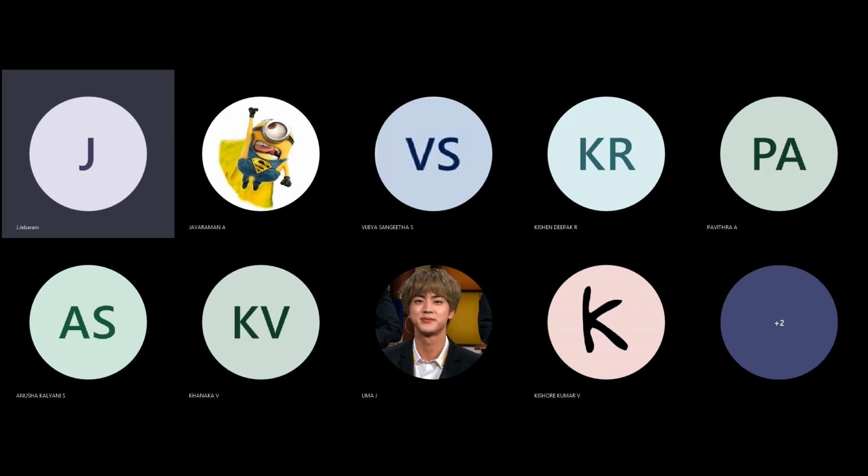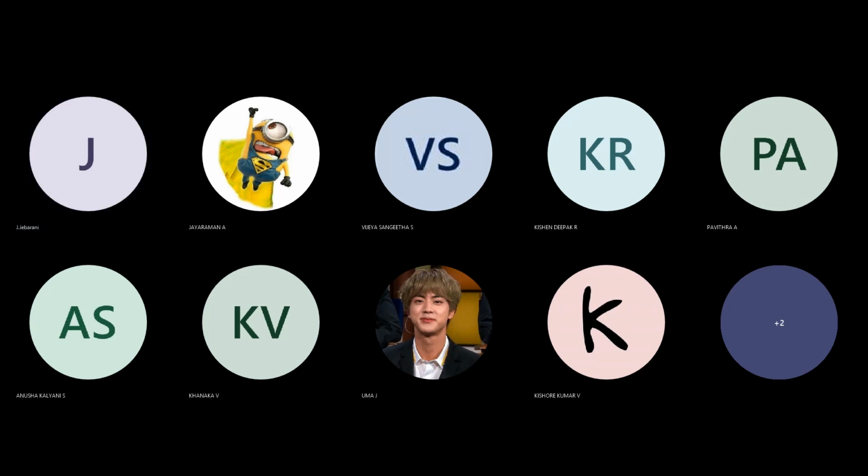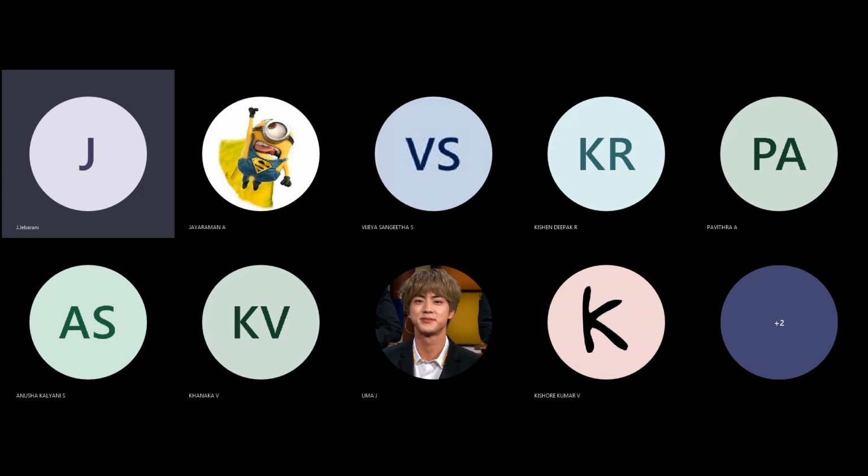And the third approach is called overflow. Here the mold cavity is completely filled with melt and closed off by the wall. Then a separate pin is opened in the mold section for water injection. Simultaneously, the valve at the end of the cavity opens a path from the main cavity into a second, overflow cavity.